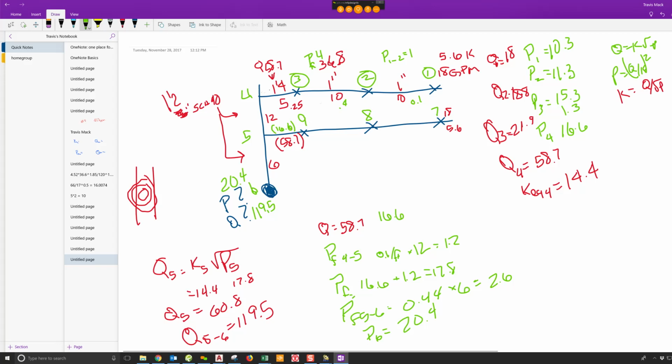Let's backtrack just a bit here. This was something that I didn't do. Now we're going to add fittings into all this. So we need to know where to add a fitting. NFPA tells us that we don't need to include the fitting for a sprinkler that's screwed directly into a fitting, because that's built into the K factor of the sprinkler. But if we're flowing our pipe here, we have to figure out which fitting, because we're coming to a fitting that changes flow 90 degrees. We need to know how to figure out what fitting we're using.